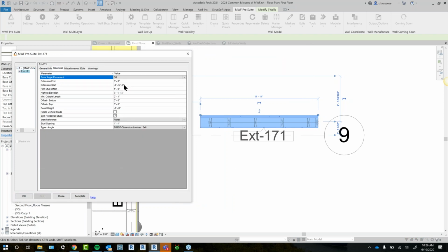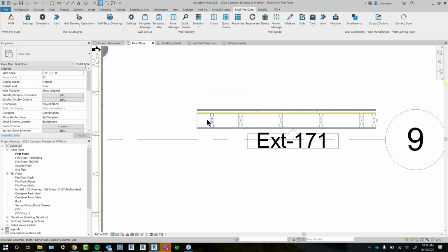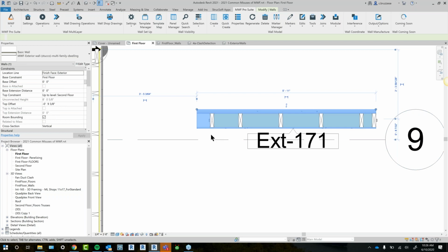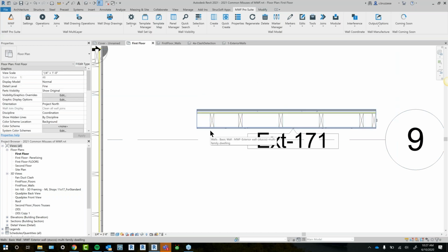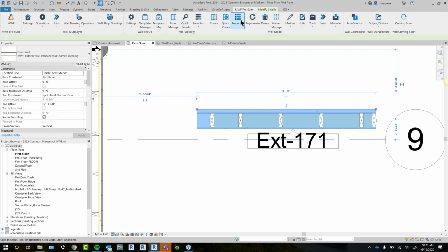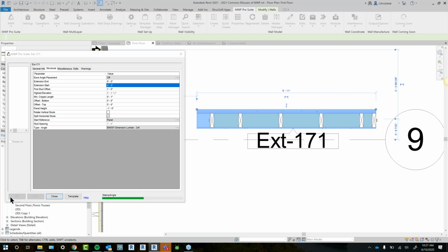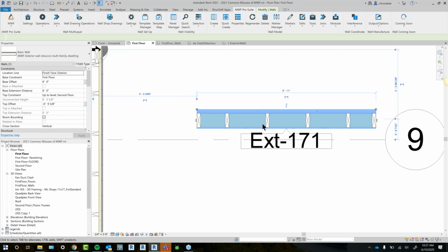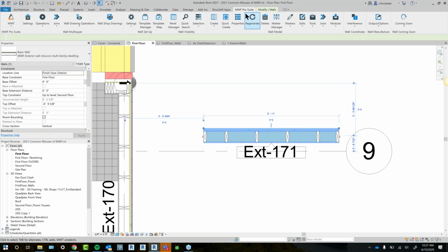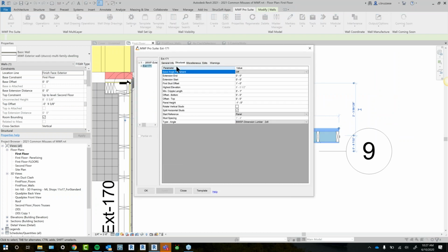So on this wall with no connections, where I obviously don't want that offset, it's going to basically give me 5.5 inches at the beginning of my panel. So again, when you're saving templates, try to do it on a wall that doesn't have any connections to it. I realize that can not always be the case, or if you're working, you don't even have that in mind. But if you are saving or updating templates, double check your extensions, make sure those are set to 0.